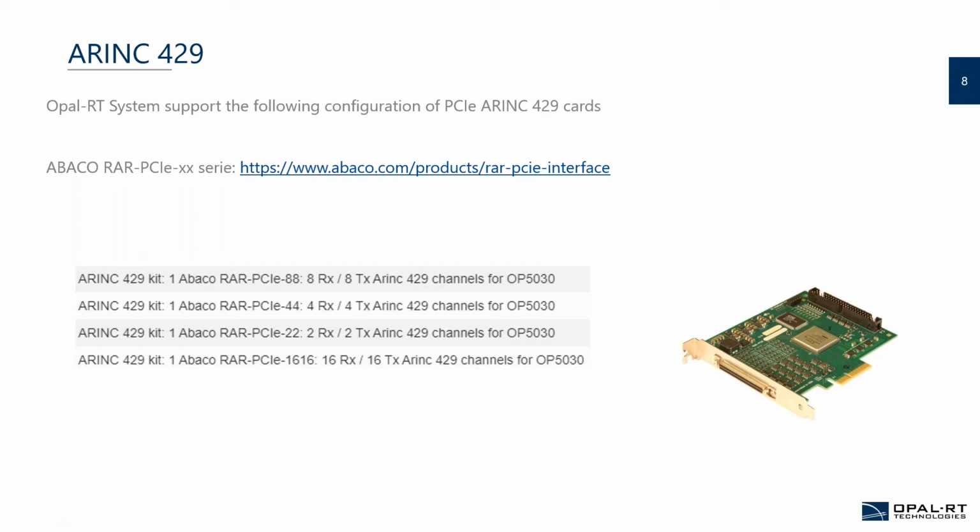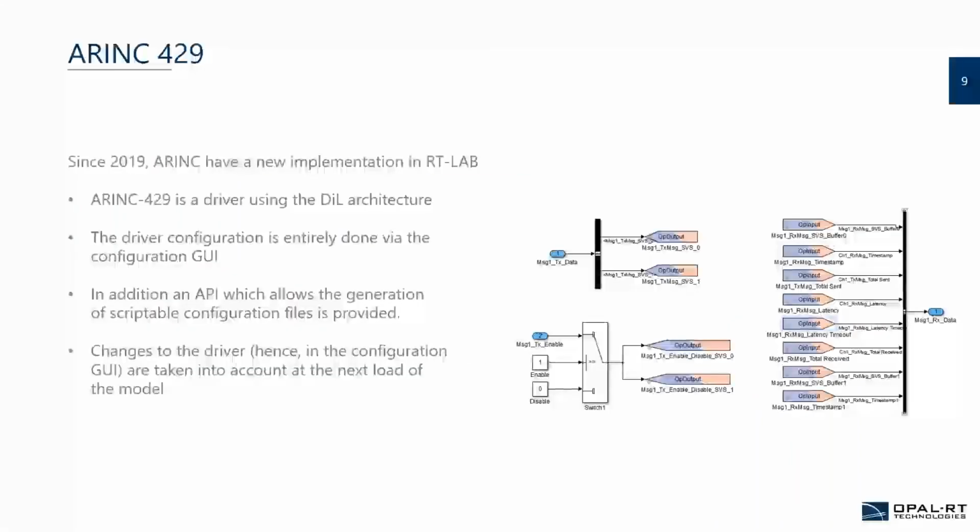So the way that we work on the new protocol of the ARINC 429, we actually make use of what we call the DL architecture. Mainly, all the protocol was embedded in the OPAL-RT Simulink environment. OPAL-RT's software is called RT Lab, and RT Lab uses Simulink as a modeling tool. We put all the driver functionality and configuration into the Simulink environment at first.